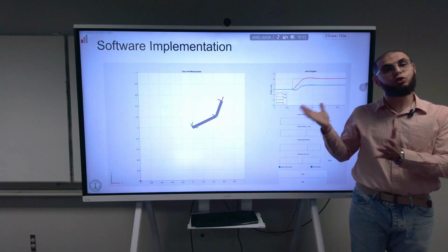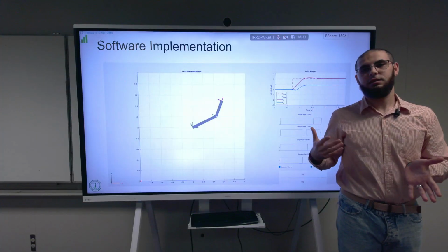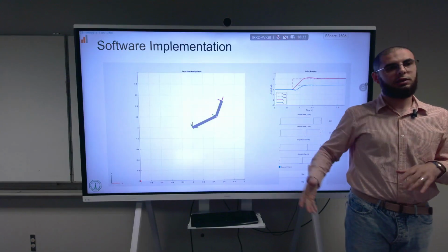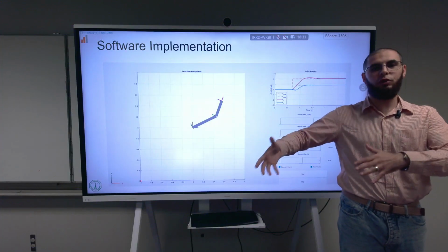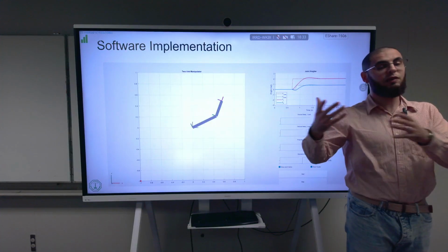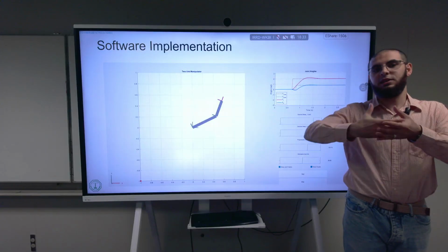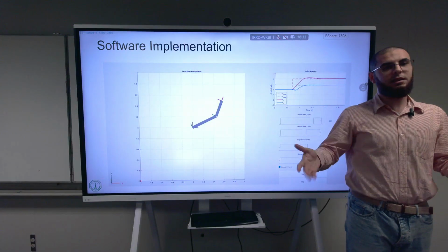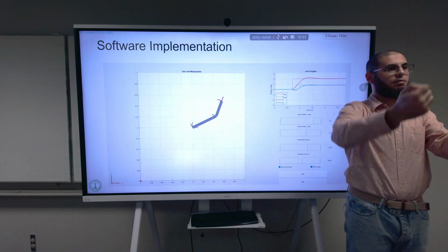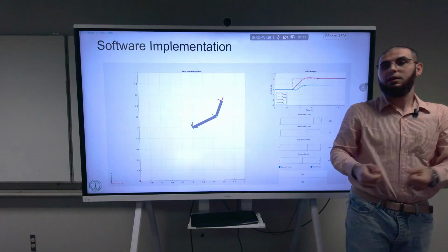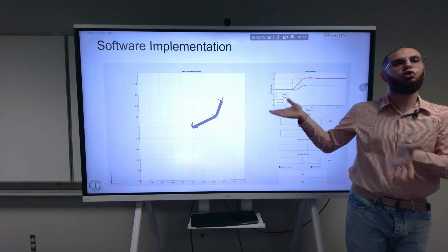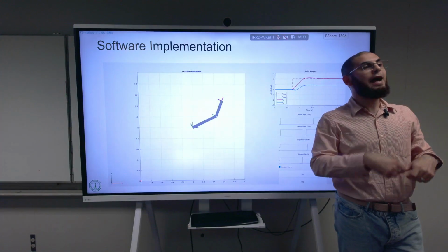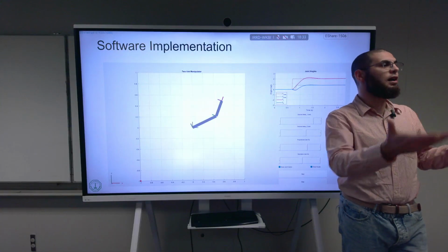For these robots, usually, this idea of modeling, stuff that you did not model. None of these robot arms are fully rigid. And it becomes even worse as you go into applications, for example, if you have a drone. If you want to have a robot arm on a drone, it's impossible that I can design the robot arm to be very rigid. I need to make it flexible. And flexibility means actually that the system itself has stiffness on its own. And the equations of motion we derived don't take that flexibility into account. The joints themselves can be flexible. And this will introduce all of these high dynamics.